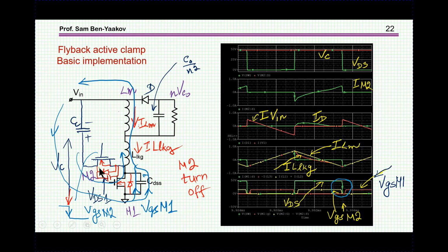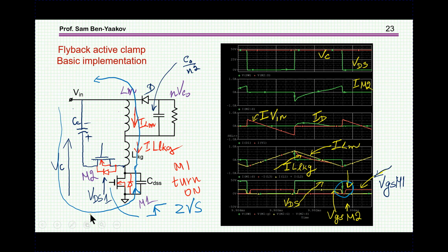And then once we do that, we start having all this current coming back. We have through this capacitor current, we have through this capacitor, and eventually we're going to have through this diode. So this current, as it goes up, will cause this voltage to drop because we are now discharging these capacitors, and the voltage will drop. We see the voltage dropping. This is the VDS dropping, and eventually, of course, this current will pass through the diode only when the voltage reaches zero, actually a little bit negative, say -1 volt.